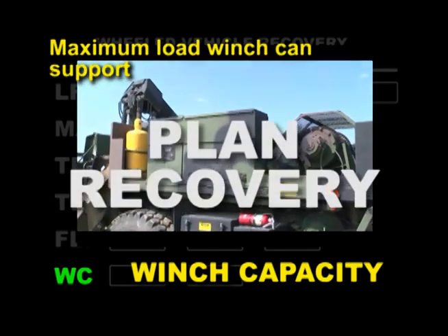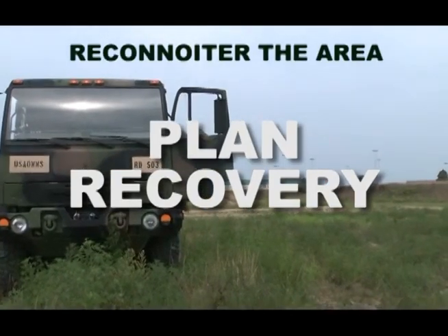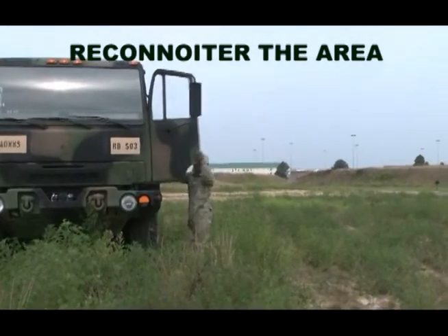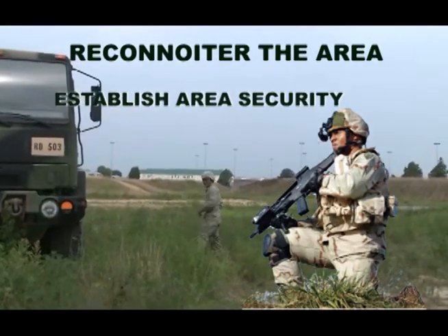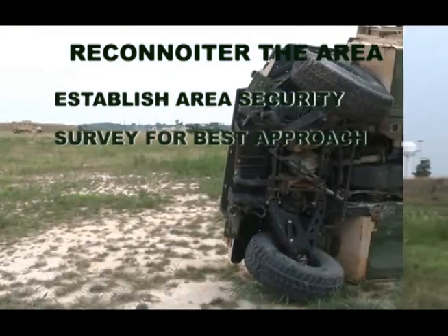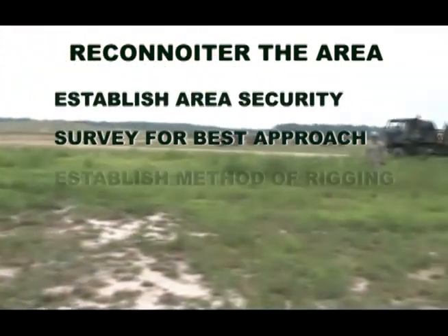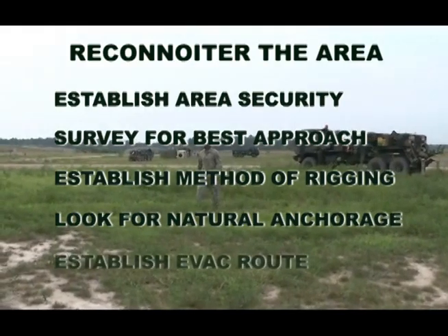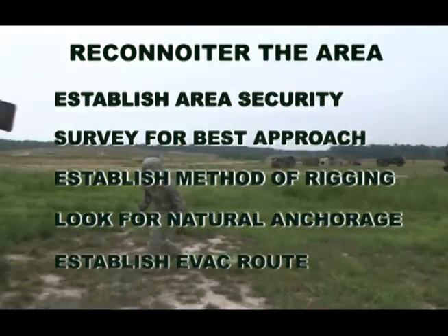Now that you are familiar with the common terms, let's plan our recovery. The first step in planning your recovery is reconnoiter the area. During this step of recovery, you should establish area security and then survey the entire area for the best approach, method of rigging, any natural anchorage, and an evacuation route. A good recon of the area will prevent possible disablement of the recovery vehicle.